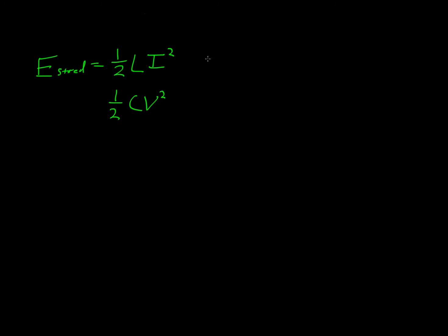Okay. What about the actual voltage over your inductor? Well, your voltage over your inductor is going to be equal to your inductance times the derivative of your current with respect to time. Okay? The AC equations we'll get into later. This is about all for the inductors as far as the current and voltage equation goes. One thing to note, that once it reaches steady state, the inductor acts as a short circuit in a DC circuit. Okay.